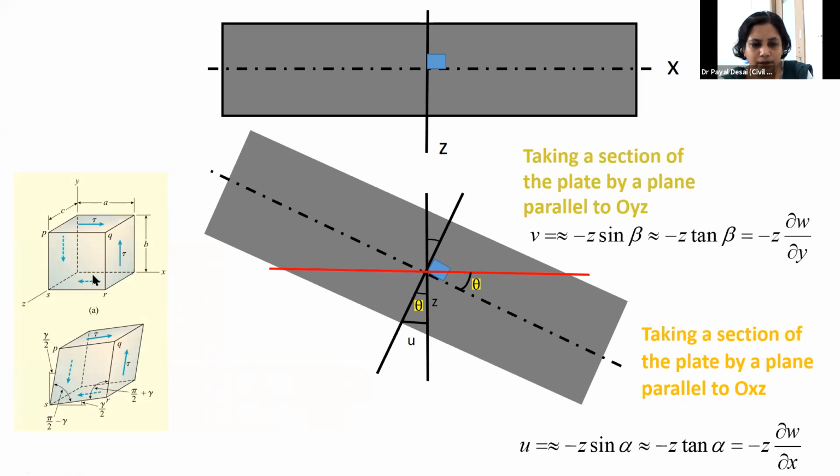Okay, so when you have the axis of the surface, the front surface of the plate is the x-axis, and this vertical line, which was initially straight, at 90° to the x-axis, even after deformation remains at 90°. So basically plane section means a cross section. The plane section remains plane before stretching and after deformation.